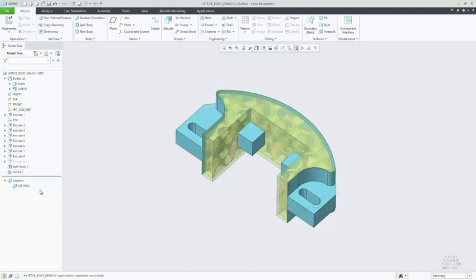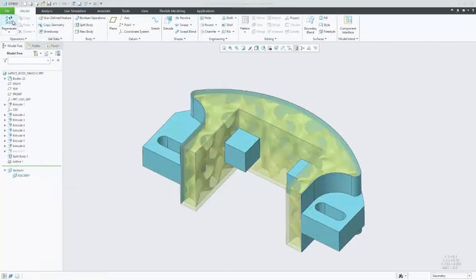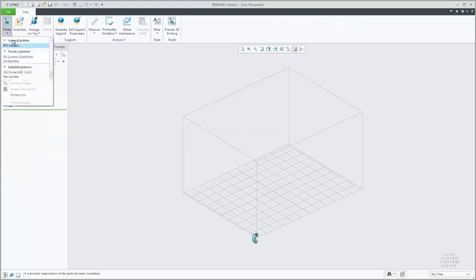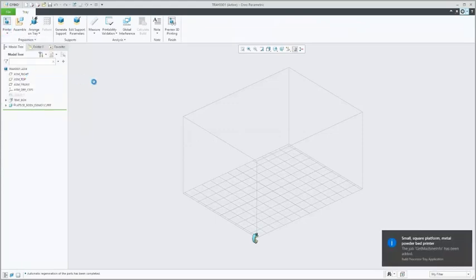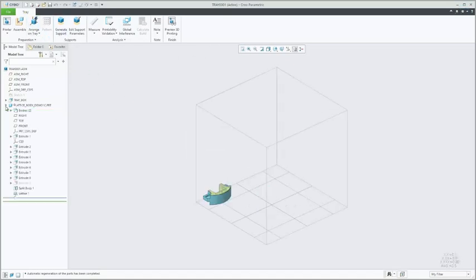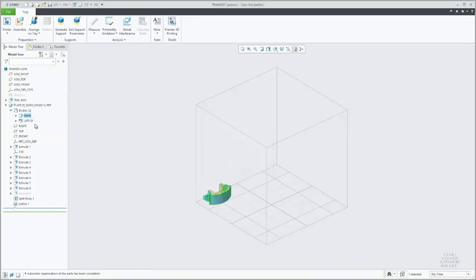Beyond lattice creation, multi-body capabilities further enrich additive manufacturing related workflows through the ability to perform a clearance validation between bodies, to assemble a multi-body model in the 3D printing tray, and if you work with a 3D printer connected through Materialise build processes, you can define printing strategies by assigning different printing and build profiles to individual bodies. That means you can, for example, vary the laser power or other parameters when printing the lattice body versus the solid body.